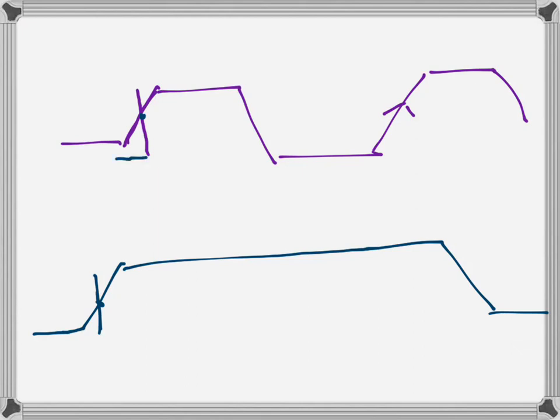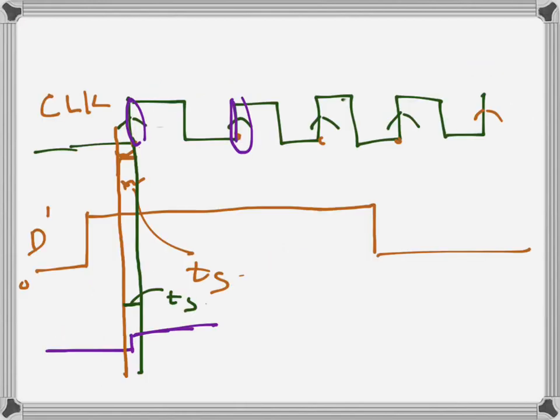Now if we talk about hold time, that's exactly the same. It's only after the clock edge comes. So after the clock edge comes, how long can the input not change? If the input changes before that, then again the input becomes invalid. So the output becomes indeterminate and the input becomes invalid.